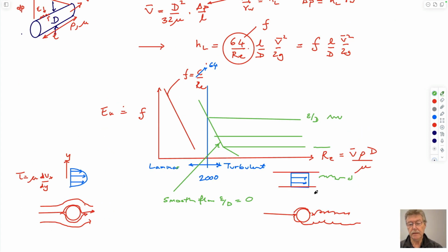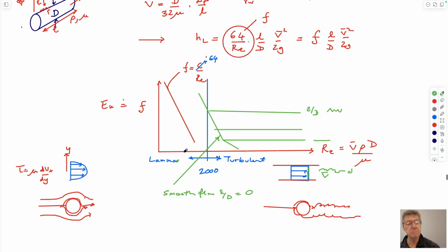And so this would be exactly that. If you look down this tube, you'd see vortices, but on average, this would be a straight line across here, right? If you went across here, the instantaneous velocity might be a lot in one direction or the other, but the average would be some magnitude, which is given by V bar. So we can use this chart. We can get this chart without any differential equations just by using dimensional analysis. And that's how it was derived in the first place.